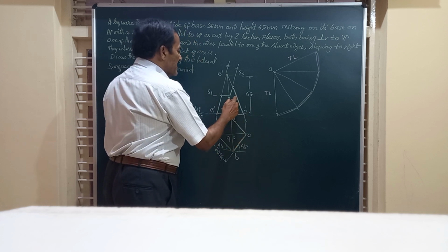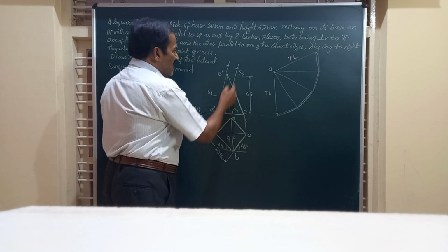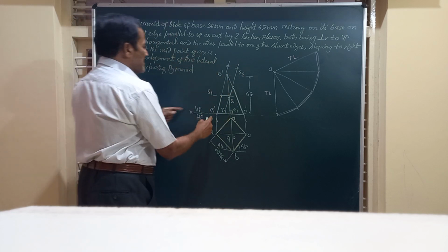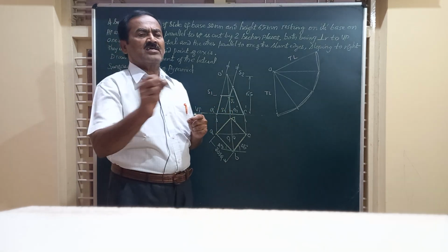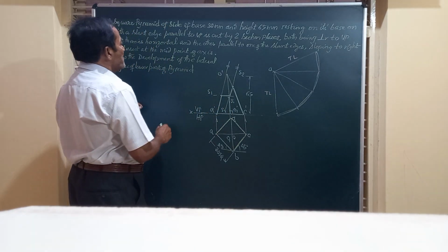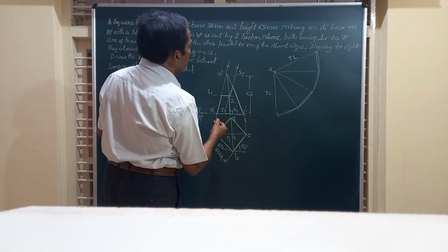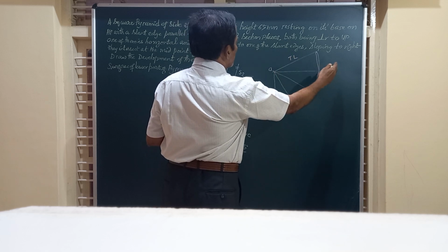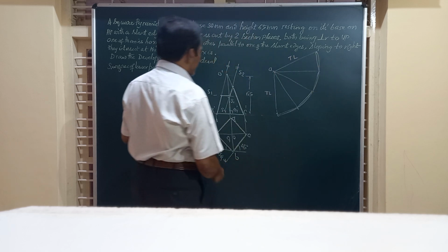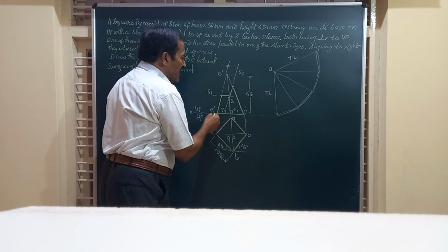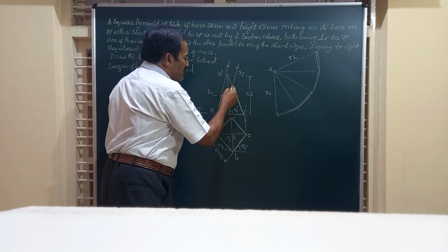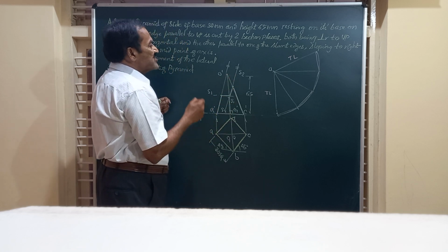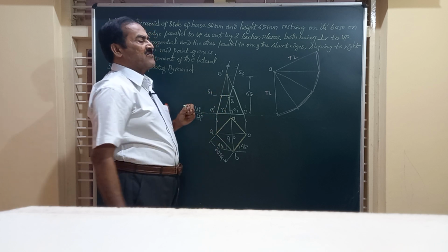One is horizontal. I call that as S1, S1, and the other one is S2, S2. Section plane, one of them is horizontal. So S1, S1 indicates a horizontal section plane. Whereas the other section plane is parallel to the slant edges and sloping to the right. So friends, this is the slant edge O dash A dash, and this is the section plane S2, S2, which is parallel to this, and both of these meet at the midpoint of the axis.